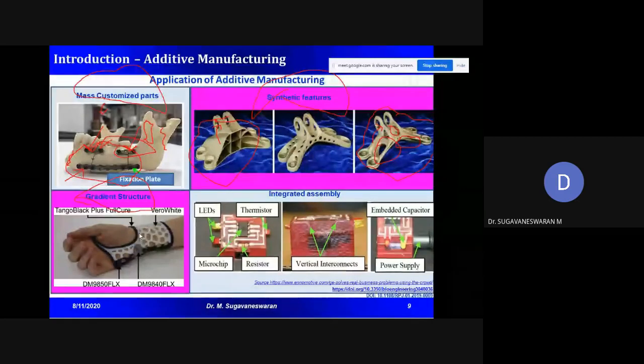So the rigidity of the material is arrived at based upon the misalignment, and the contour is based upon the patient profile. And you have flexibility in the material. The black color region is very flexible, so you may not face any problem. If you provide the same flexibility at this place, then you may not have proper stiffness. So this is another example where you can go for a customized product with a gradient material.